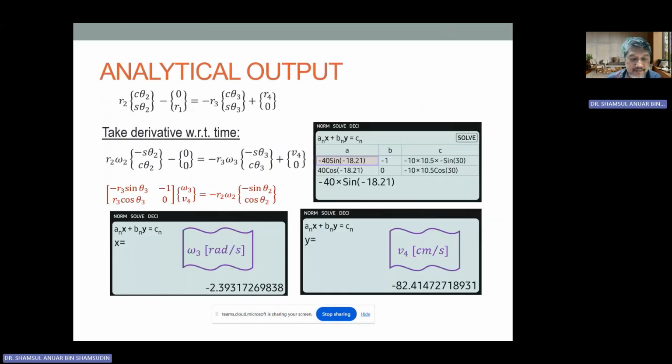All right, similarly, if you are solving this purely using the vector method, and you do not have access to CAD or maybe drawing manually, you can set it up in this manner, and then take the derivative with respect to time, and the R will be the same here. Okay, and then cosine theta 2 will become sine theta 2, and sine theta 2 will become cosine.